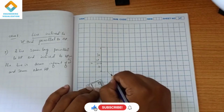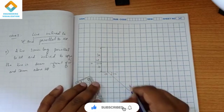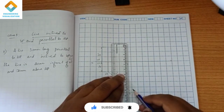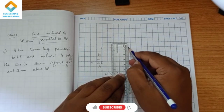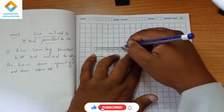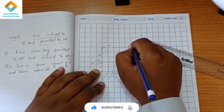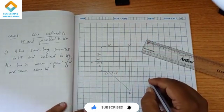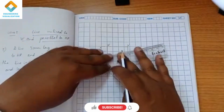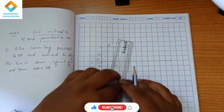This is A, this is B. Now projecting upward, here we get the front view. So this is A dash, B dash. So this completes the problem. You can see this is the true length of the line. So it is 50.